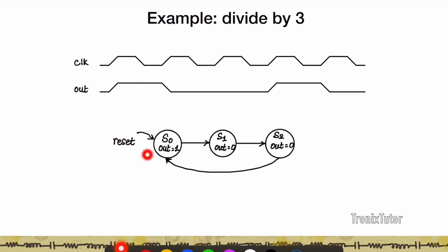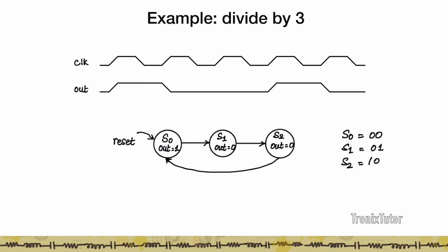And like every time when you do good logic, you want to ensure you have a reset signal so as to prevent any spurious interaction with inputs. So this reset is going to ensure that you start off with a 0, for example. In normal cases, the way you would set up the logic for this is you'll define the state variable. Since I have three states, I'll define it as a 2-bit number. So I'll call S0 0,0, S1 0,1, S2 1,0, where S1, S0 defines the state.